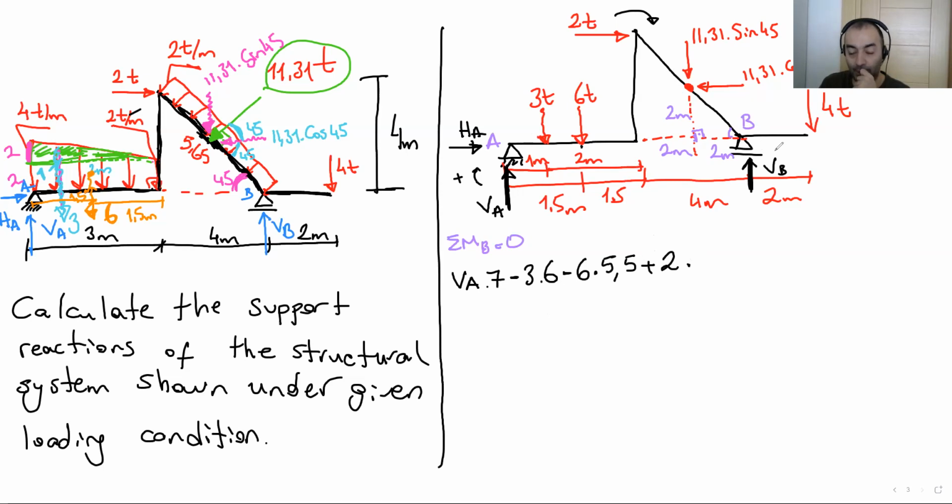What is the distance to B? The perpendicular distance, by the way, because we are calculating moment. What was the moment? Force times perpendicular distance. Okay. What is the perpendicular distance here? Yes, of course. You're right. 4 meters. So basically the force goes like this. The perpendicular distance here, 4 meters. Totally 4.